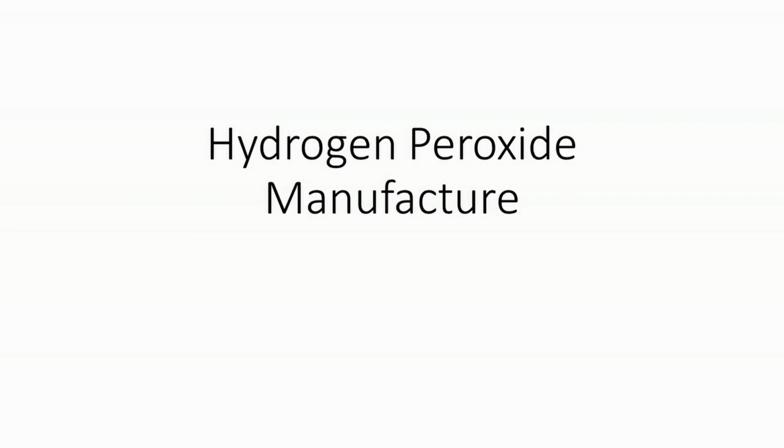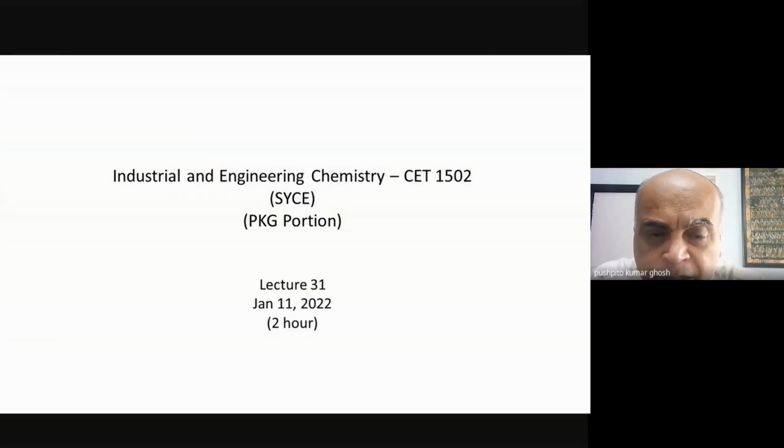Good morning, everyone. Last time we ended talking about how even though the ethylene to ethylene oxide with silver catalyst was an excellent technology, you could not even use it for propene. And so one had to use a different method. Either you go back to the chlorohydrin based process, which generates waste, or one could actually do an oxidation with hydrogen peroxide with a titanium silicalite catalyst, which we discussed. It is a very famous process now. It is known as the HPPO process, which is hydrogen peroxide to propylene oxide.